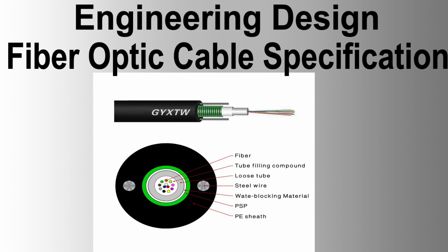Trenching. Excavation equipment. Only light and approved excavation equipment is allowed for the excavation of the cable conduit trench. The contractor shall obtain approval of the excavation methodology as part of the conduit installation procedure.